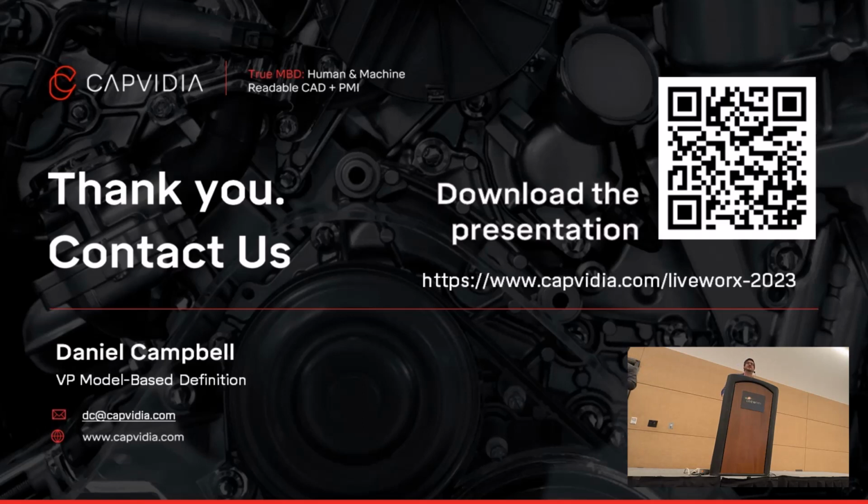Yeah, I'm curious, the settings, when you're exporting and importing the QIF, do you have a similar type of filters that you have with STEP? And then for the surface information, are you still managing it using something like the insertion value inside the STEP file that manages the actual resolution of the geometry? Because that can get you in trouble if you don't match them up when you do the exporting and import, so you might wind up ruining the geometry. Is it more foolproof than STEP file? It's a perfect question to end on.